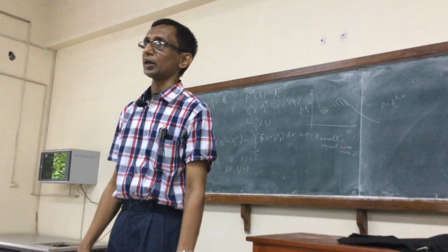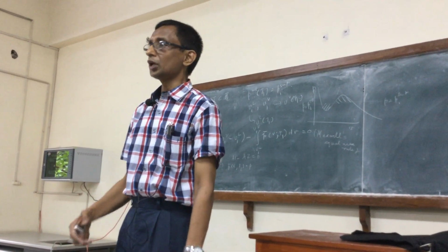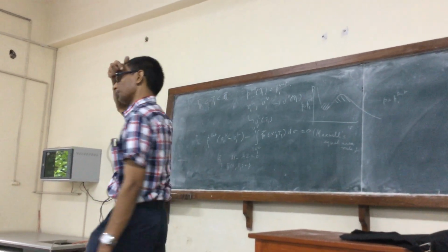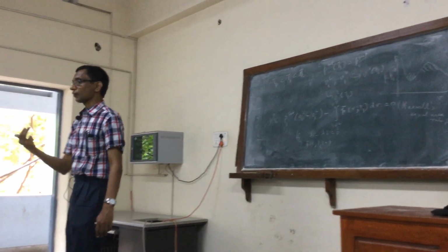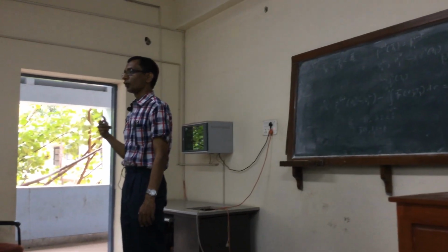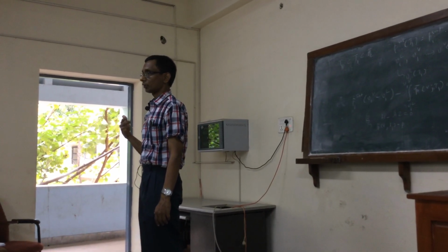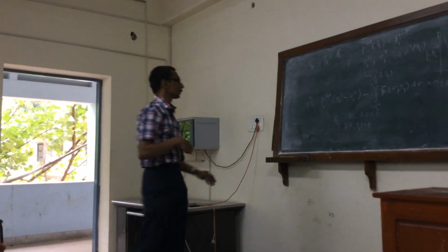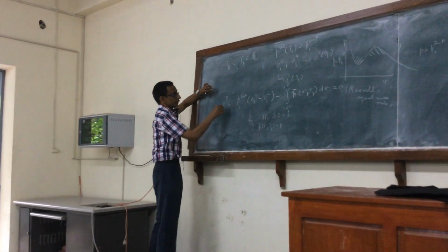We came to a stage where we have to change the pressure. We take an initial pressure that lies between PA and PB. If it doesn't satisfy the equation, then we need a way to update the pressure in the iterative process. So for that, it's useful to look at this.